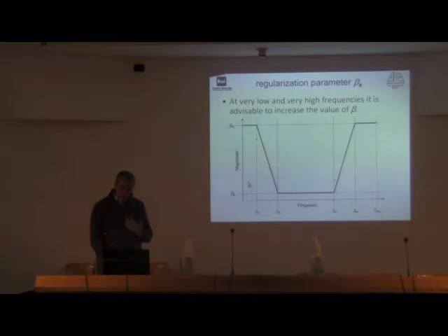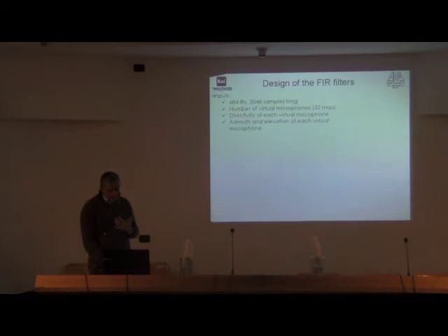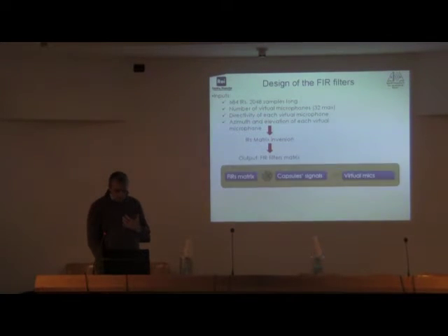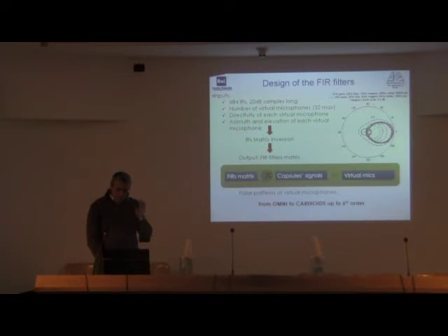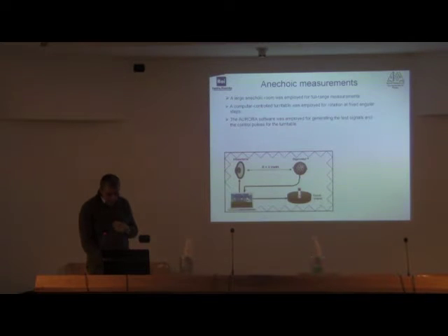We apply a regularization parameter. We make the inversion very accurate in a central frequency range and less accurate at extreme frequencies, very low and very high. This summarizes the whole process. And we can create directed cardioids, ultra-directed cardioids up to 6 orders.